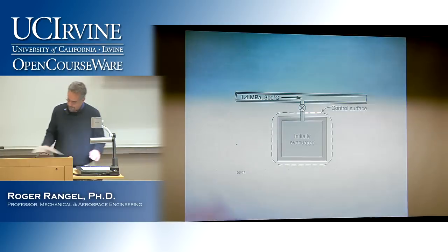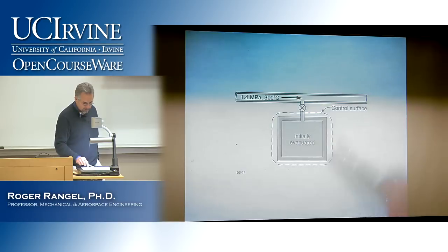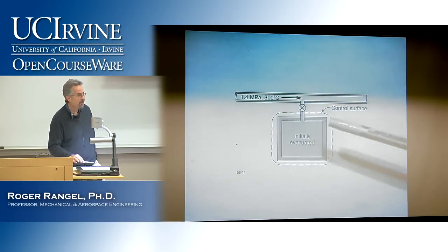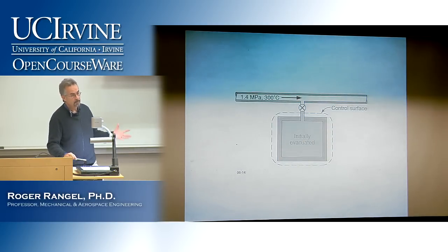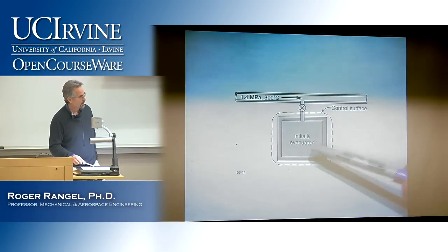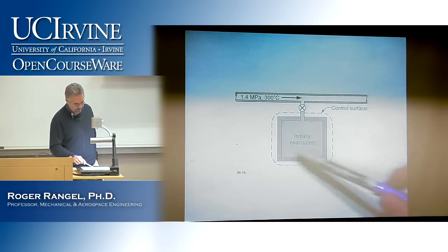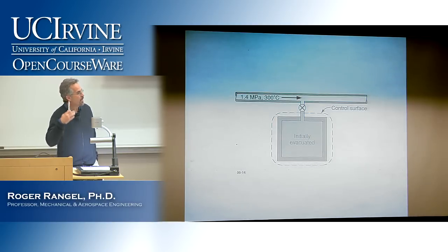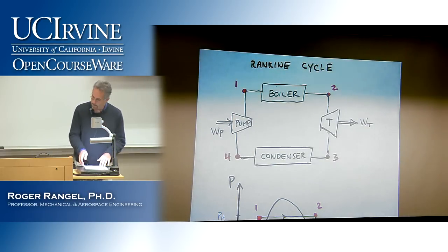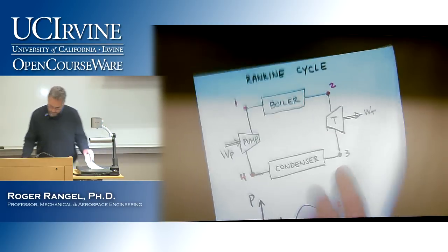And then there are these problems where clearly the situation is not the same at all times. So for example, if I look initially at this tank, it is empty. If I look halfway through the process, then it's a little fuller. And then if I keep going forward in time, I get more and more mass. So this is an unsteady situation. The state within my control volume is changing in time. Whereas, to re-emphasize, in a problem like this, if I'm looking at the turbine, I will look at the turbine as it is continuously running in steady operation. Those are the two types of problems that we're going to be looking at.